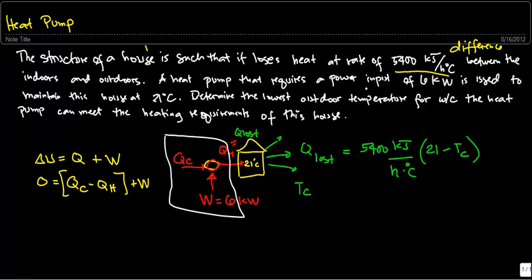The difference is actually given by this delta C, in degrees Celsius, meaning in every 1 degree Celsius difference between the temperature of indoor and outdoor, you will be losing heat with this quantity, 5,400 kilojoules per hour per degree Celsius difference. The heat you lose will be this amount times the temperature difference. If your surroundings and your house are at the same temperature, no heat is lost, right? You maintain it. So Q loss will be 0 if that is the case.